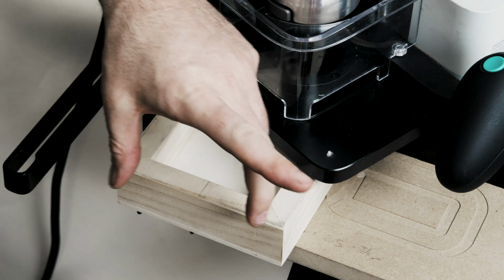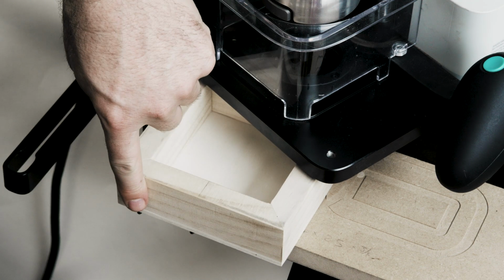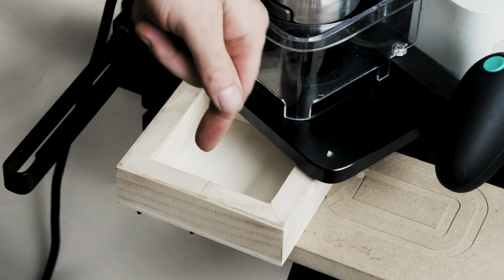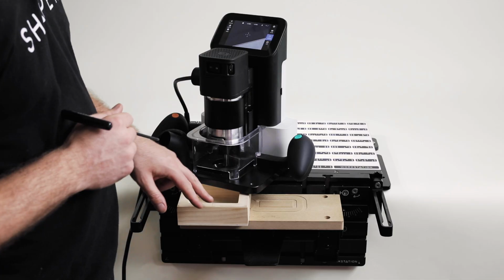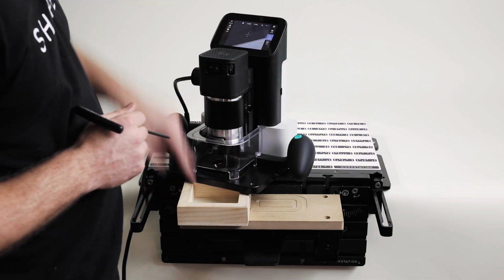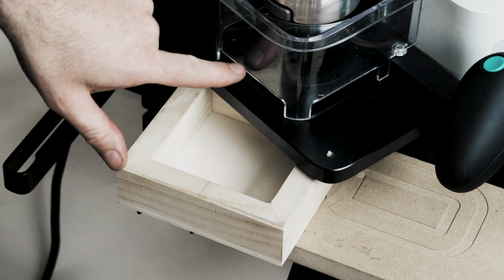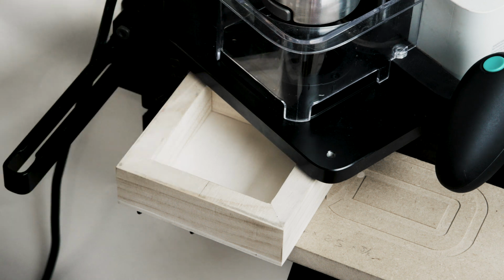So this will be our hybrid probing method where we do 2 physical probes and then a visual probe using the point of a cutter to reference this pencil mark. We're not going to use the screen scanned raster image of this that we see in our workspace. We're going to literally look at the tip of our cutter. So we'll go through the motions of that now.